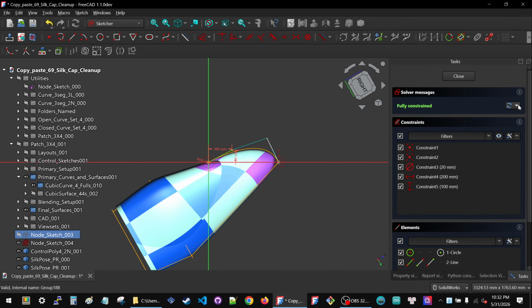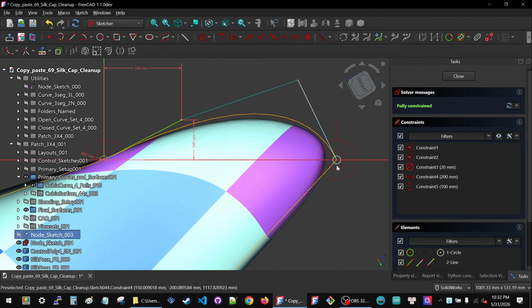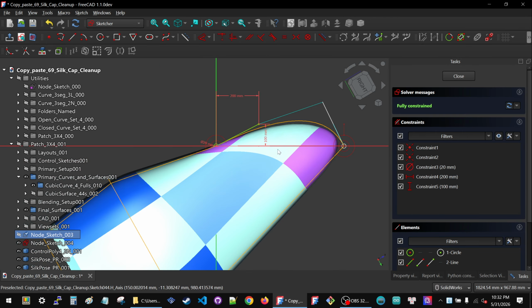Okay, remember, I'm going to turn auto update back off here, because I'm working with the high quality final surfaces, and now this will affect the entire model. And so this means slow update, so I don't want to be stuck every time I drag a surface around. Okay? And you can see how my final surfaces correspond to these curves, and they got blended.